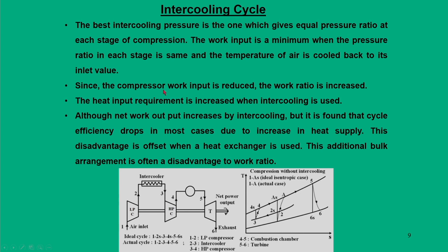Since the compressor work input is reduced, the work ratio is increased, that is what we explained already. The heat input requirement is increased when the intercooling is used. So, this is another drawback for intercooling, that your input heat requirement is increased because you need another intercooling circuit.